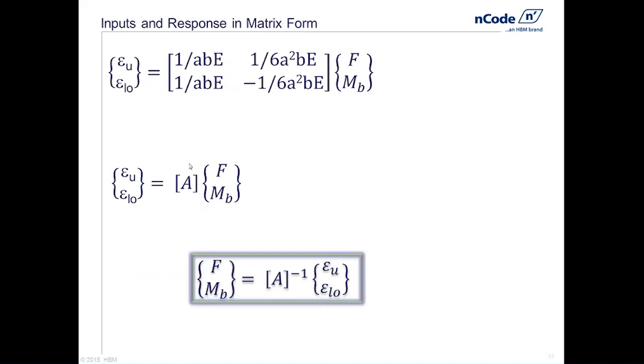Or you could think about this analytically speaking. If the geometry is a little bit more complicated, we could think about that as being the finite element response, right? The influence of a unit load. How does a unit load become a strain? So ultimately, the reason why we're trying to do this is to get to the highlighted equation at the bottom. If we know how load and strain are related, either from back of the envelope calculations, hand calcs, or by using finite element analysis, we can then invert that strain sensitivity matrix.